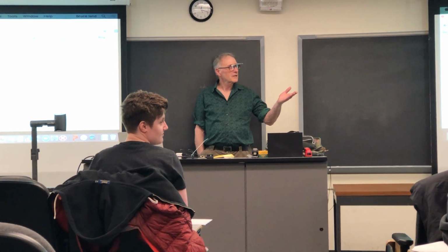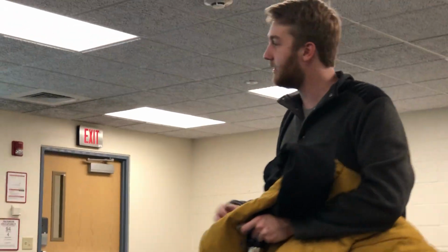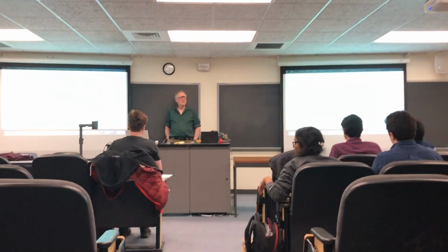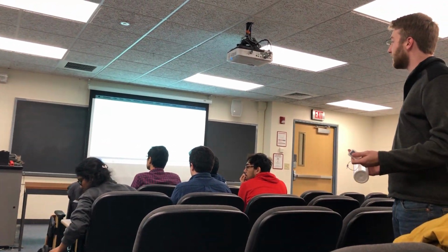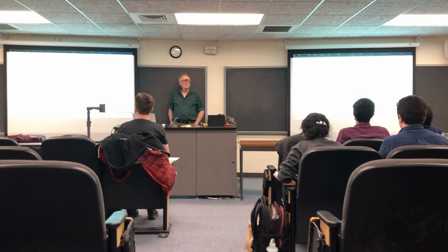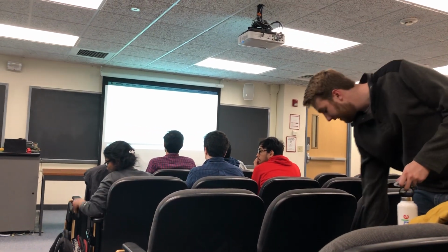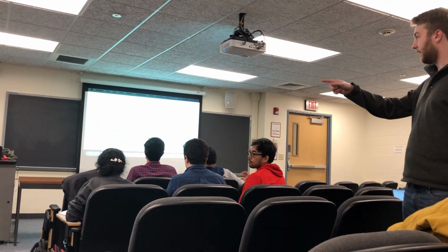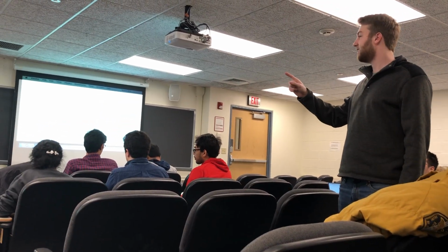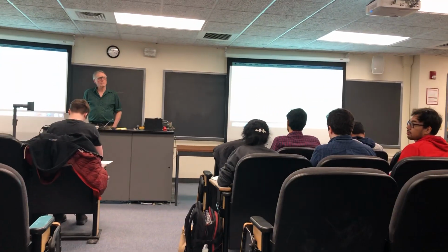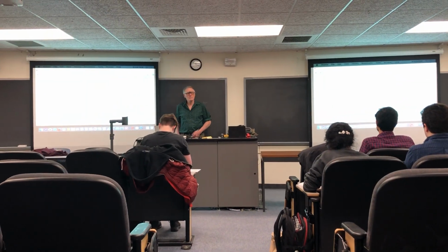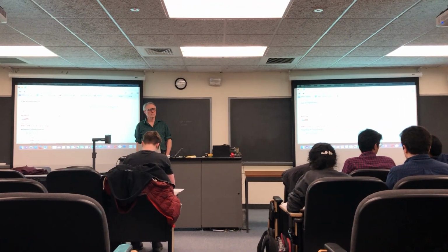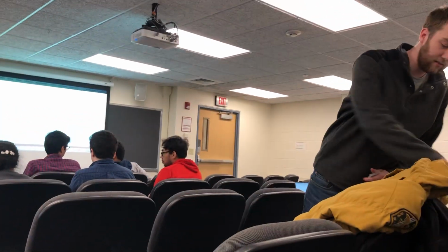We fixed it. There was a design partition hanging around from an old file that we deleted, and the clock was telling us there was a timing error because there was a piece of the design that just wasn't there. So we found it and deleted it, and then that compile didn't finish, it just took forever. We think we were using too many registers or multipliers, logic elements or whatever. We reduced it and it finished easily. So it was definitely something using too much.